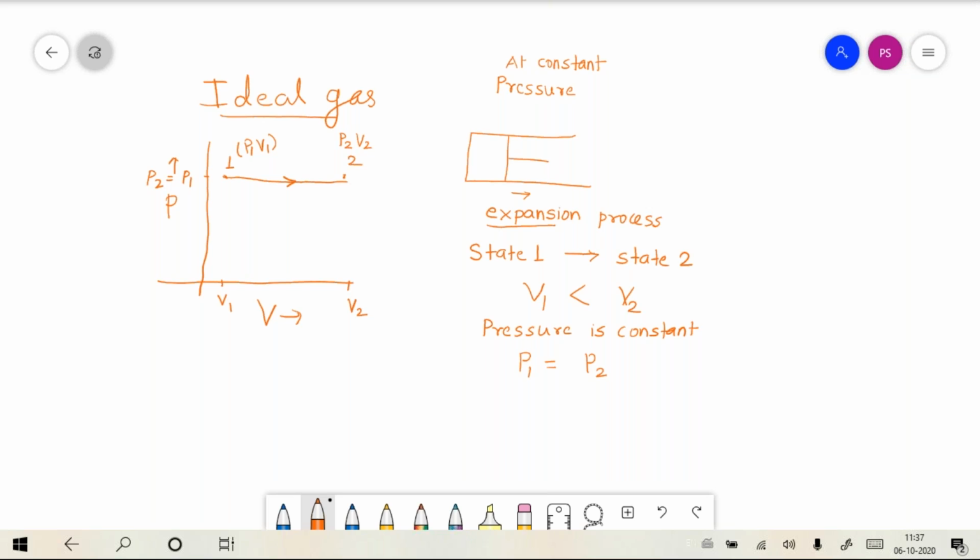Let me first discuss now the diagram which I had drawn here. This is a piston cylinder arrangement. Let me ask you whether this is a closed system or an open system. Tell me this answer in your question column. Whether this is a closed system, the diagram which I had drawn here, or it is an open system, and why? Vedant is saying closed.